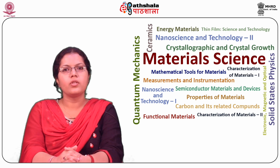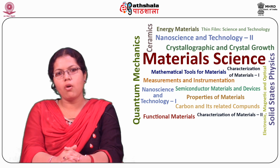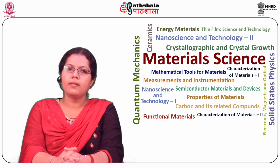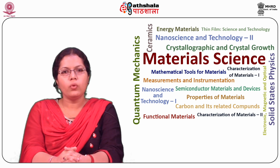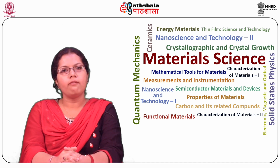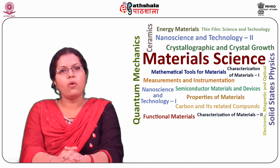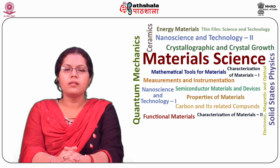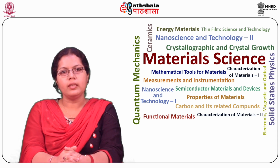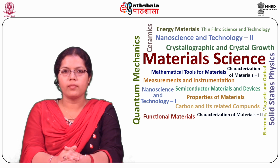The inductance should be independent of the value of the passing current. This requires that no ferromagnetic materials should be used. When we use ferromagnetic materials, the value of permeability and hence inductance is dependent upon flux density, which in turn depends upon the current flowing in the coil.